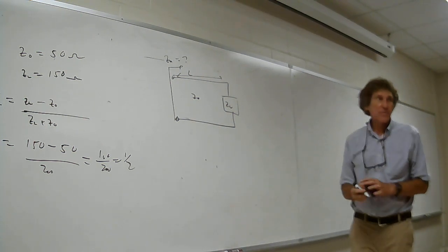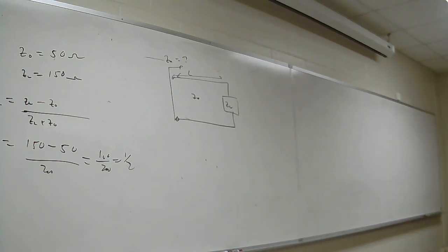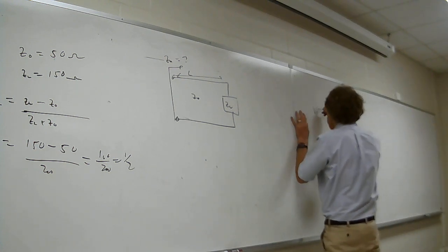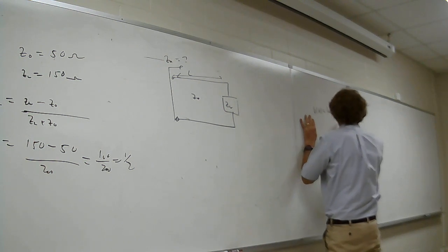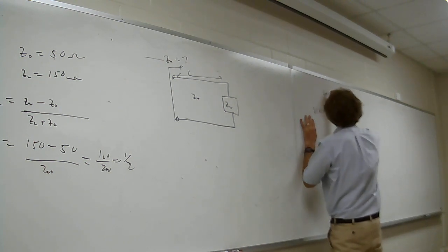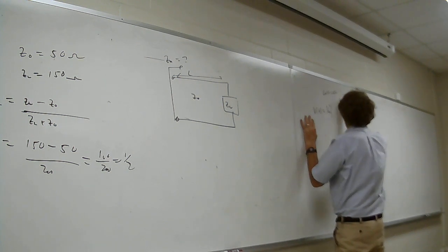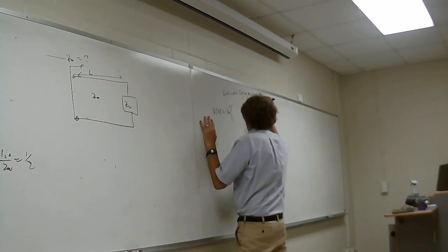When you take a look at the voltage equation, you can put your pencils down, just look at it and listen. In general, anywhere on the line you have V of z equal to some V0 plus, and I'm going to do it for a lossless line. It's the same for lossy. Lossless line, alpha is 0, R equals G equals 0.